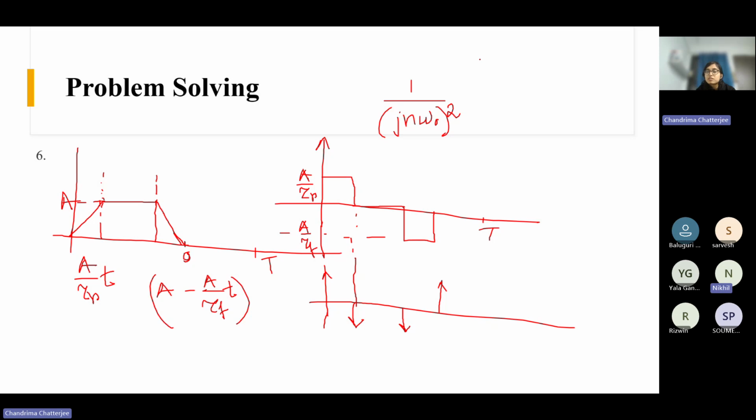So if you are doing high frequency PWM, there will be some dV by dt in the switches, right? If you are not able to do soft switching, you know what soft switching is. In those cases, if you are using SiC or GaN or also simple Si, whatever wide band gap you are using, if there is high dV by dt or di by dt, there will be EMI EMC. All these things will impact your design.